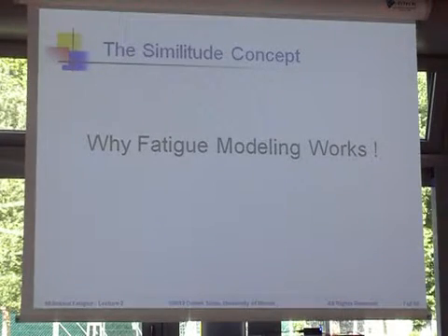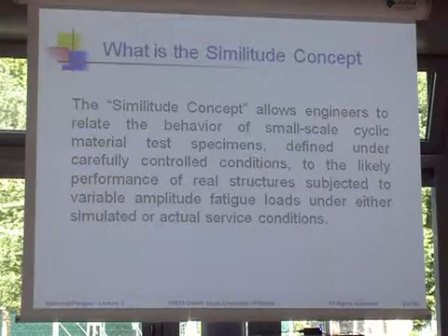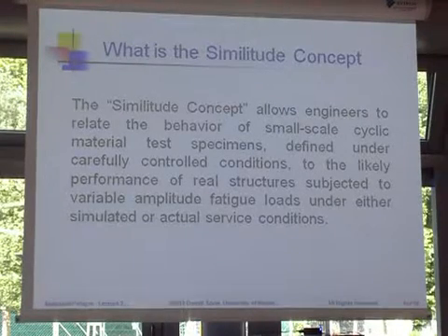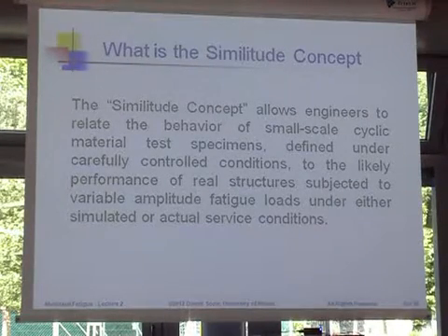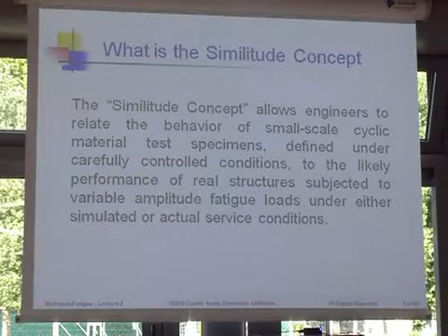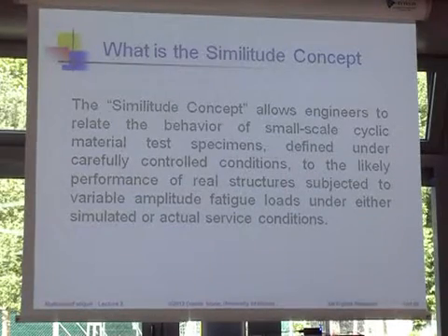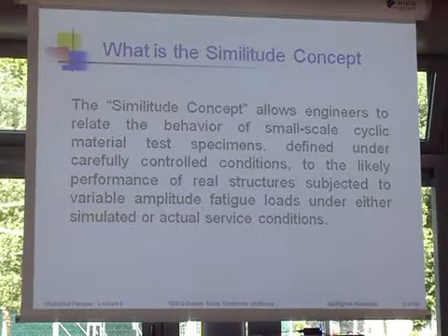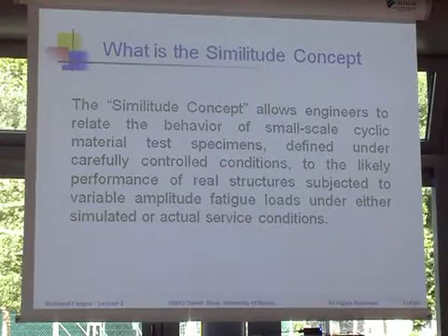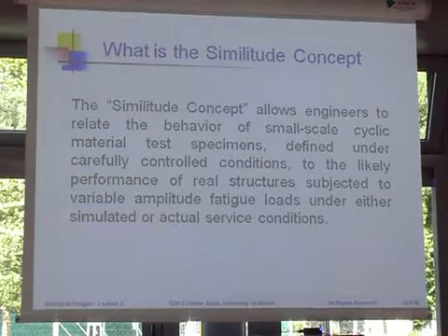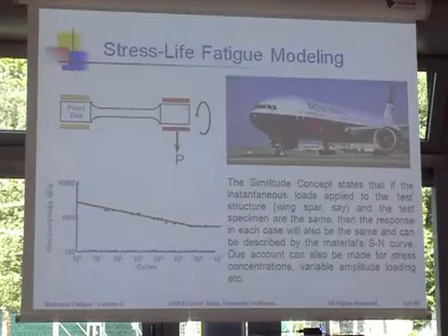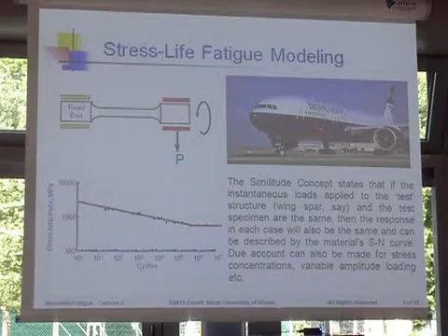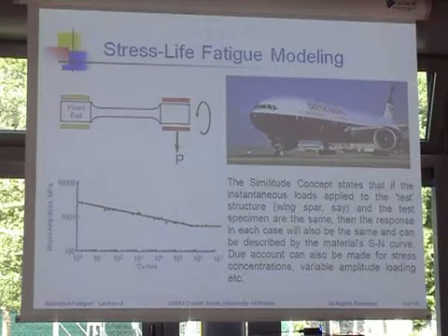So why does any of this work? Well, it works when we have the right similitude, and that is we want to study somehow materials, and we want to take what we learn from materials, and we want to use that to get the likely performance of the structure. And so that means we have to have the same failure mode. So let's just think about what happens in the stress life